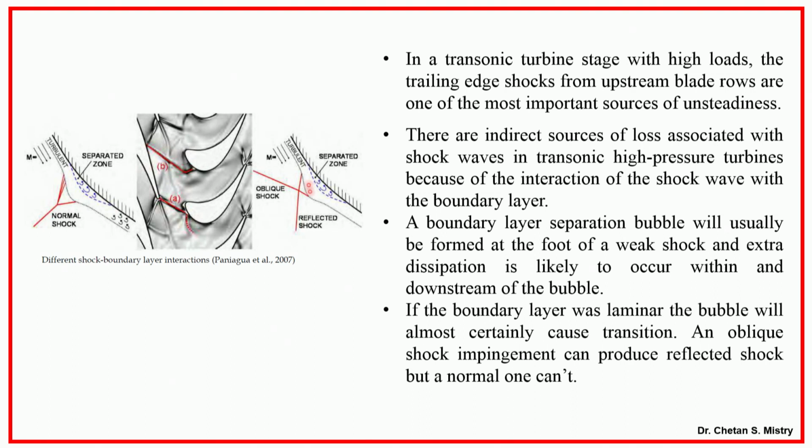Here I will have my shock boundary layer interaction, which generates flow separation in that region. Locally at the exit, I will have a shock structure forming in this direction. One of the shocks striking on my suction surface will act like a normal shock, and you will have separation of flow happening.